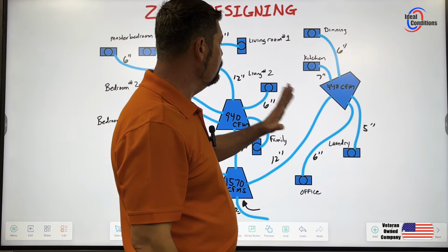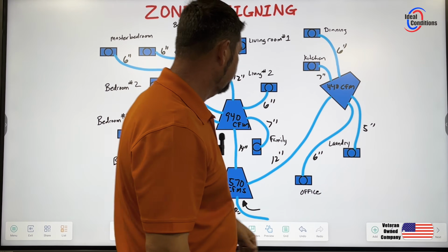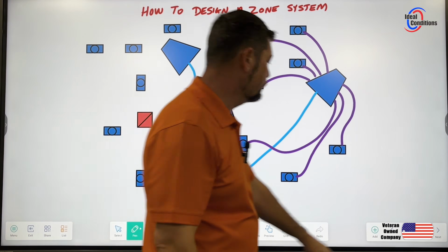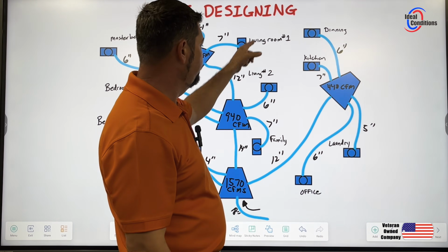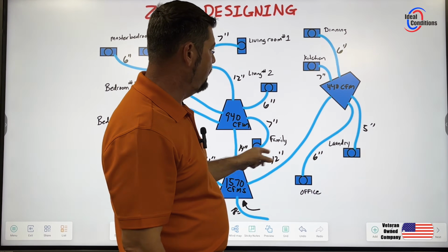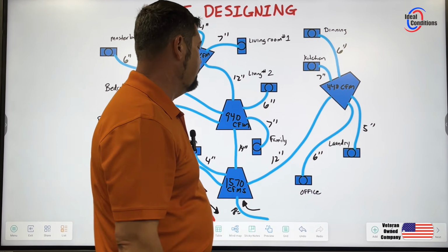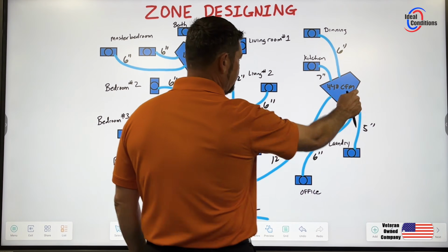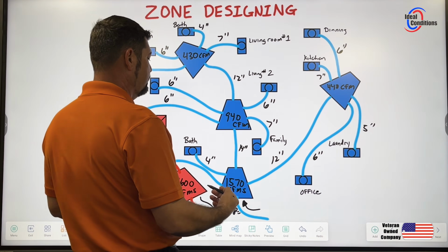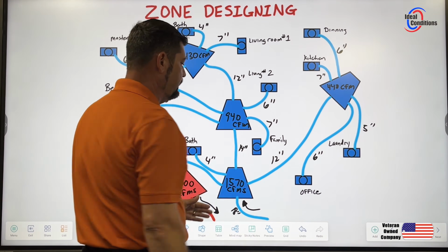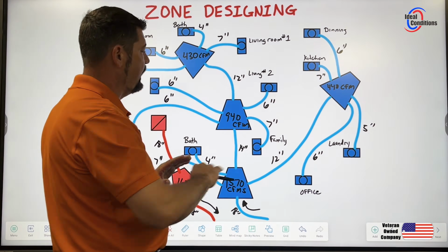So I'm adding two more ducts. I'm sorry, looks like three more ducts. Let's just look. Yeah, three more ducts. Okay, I've got four. I need to have a total of seven. So I need to put these two living rooms and put that family room on that box. Well, I could add more to that box. That's not a problem. I'm adding this family room to this side, and I'm pretty much adding these two living rooms to this side. Okay, but if I looked at that 12-inch trunk line that's feeding over here, it is not going to carry the additional loads. I already know that 12-inch trunk line is going to have to come out.